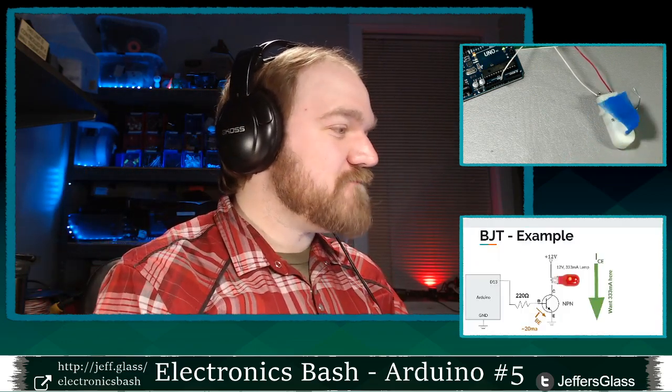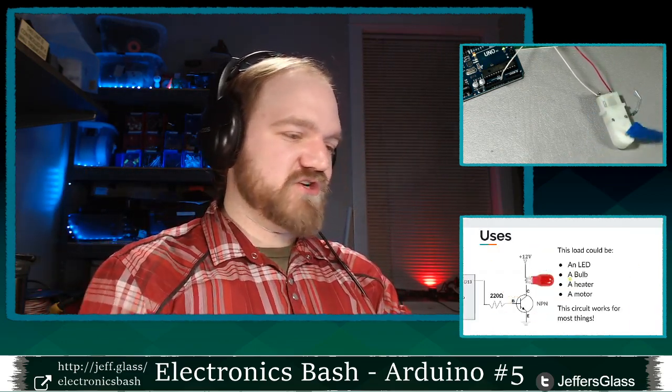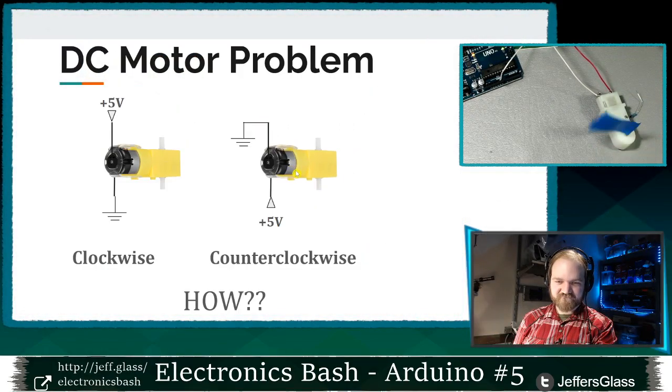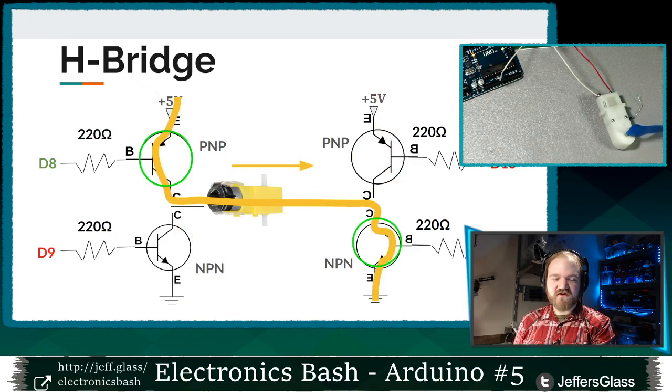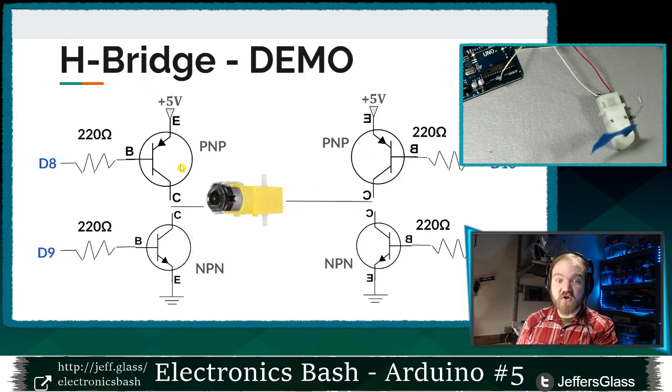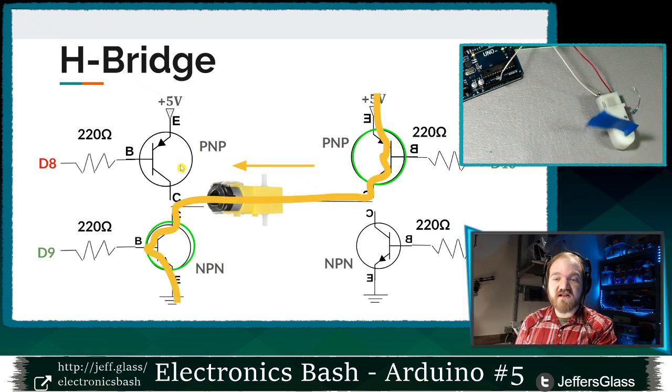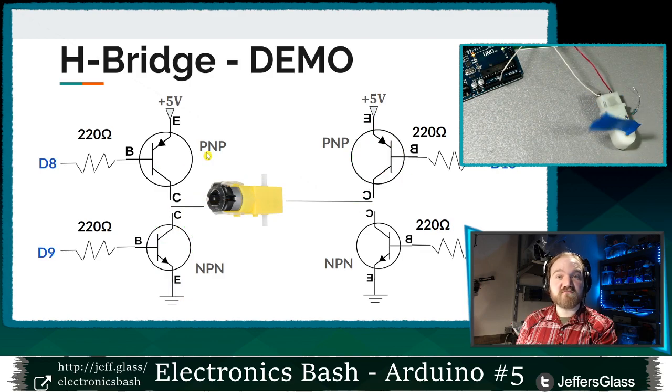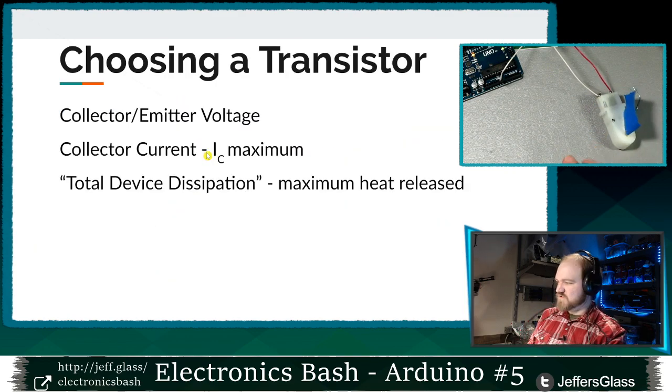Oh, right. So that's using an H-bridge to control motors. Stepping back through our slides, H bridge, right? So hopefully that makes sense. If not, I encourage you to build this circuit and play around with it. Make sure you get your digital pins hooked up correctly, and make sure that you're not blowing anything up. But I encourage you to play with an H bridge. It's a really good way of getting an understanding of what your NPN and PNP transistors are doing. Cool?